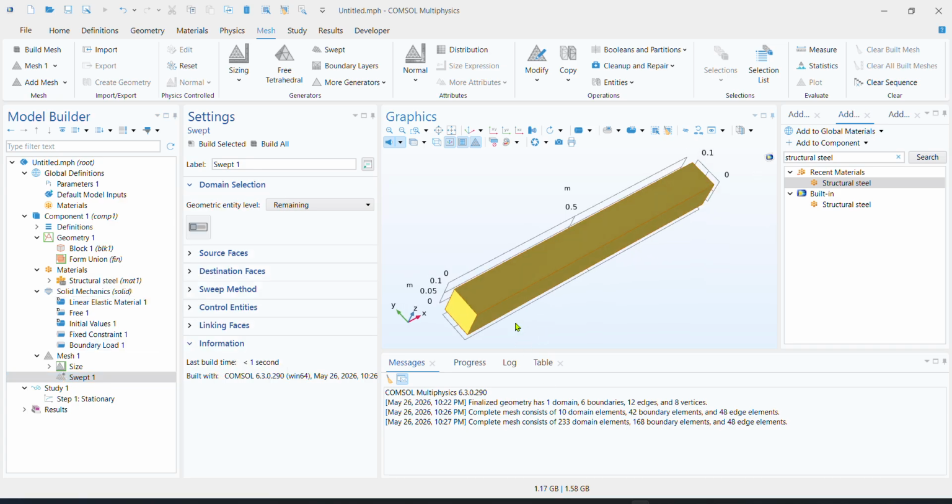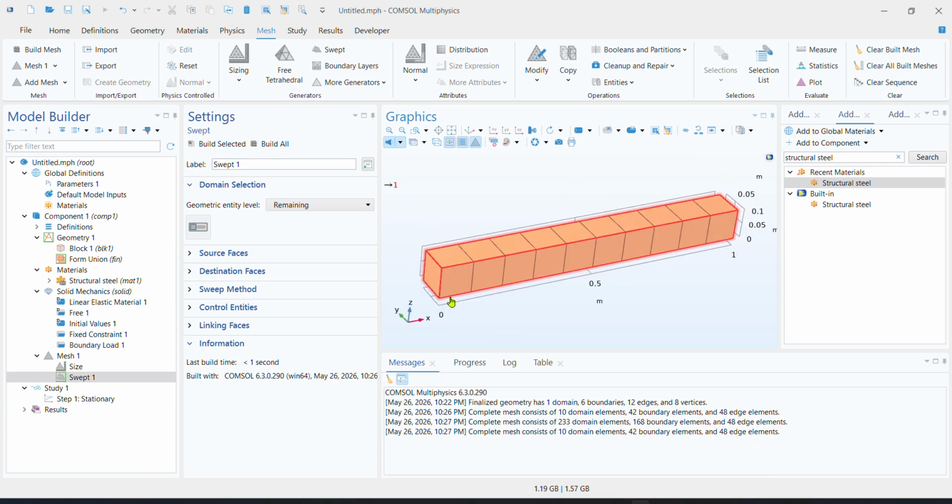Now, a few terminologies I want you to be aware of. Whenever we have a given block, this whole part of my block is called the solution space. What the mesh is doing is dividing this entire solution space into small blocks. Each of these blocks contains solutions, and at each of these individual nodes, the solver basically solves for different equations.